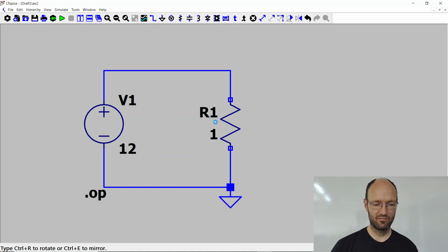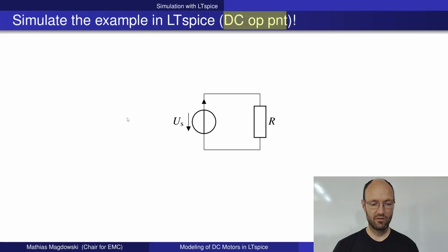We have some discussion, that's good. Yes, in the pitfalls, when you rotate the resistor, the current gets negative. This is to interpret the results, and we will see in a second why you have to know that. So if I go to the next slide, you can see not so much changes, because we take the very same circuit, and now we will do transient analysis.